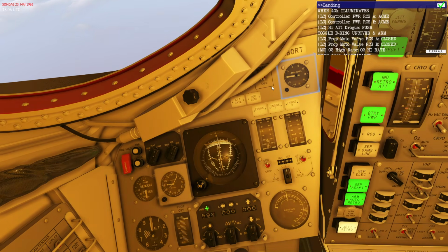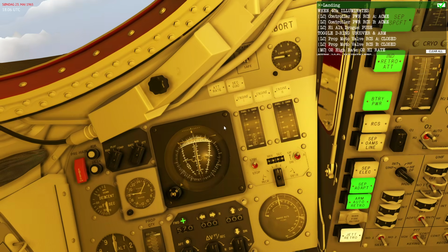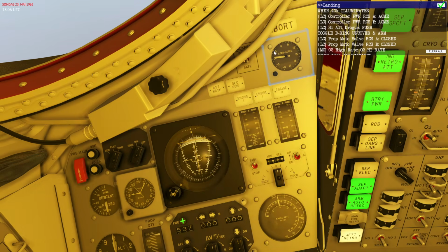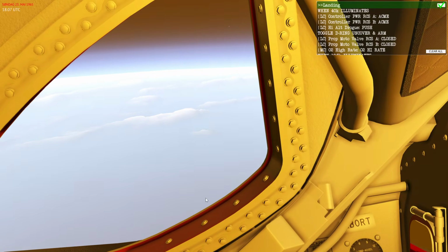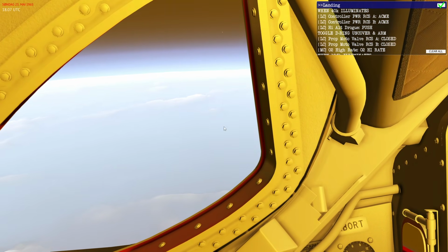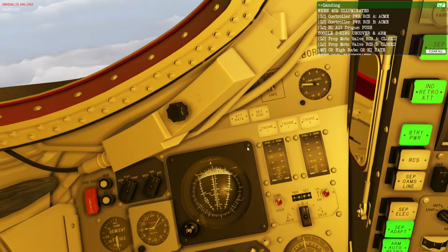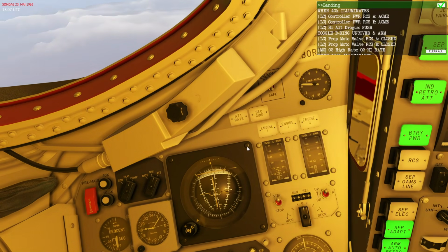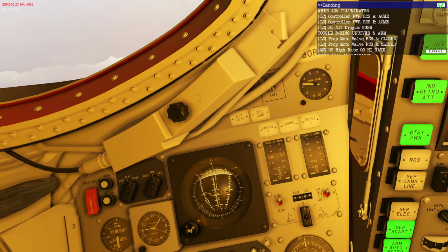Now we're waiting for that G to start building up. And in this case, just to be safe compared to just trying to hit 0 here, I'm going to roll back to lift vector up, which means heads down. So now we're heads up with lift vector down. And at 3G, I'm going to roll, so my head is pointing down and the lift vector is up. That will reduce our vertical speed and our descent rate. At 1G.